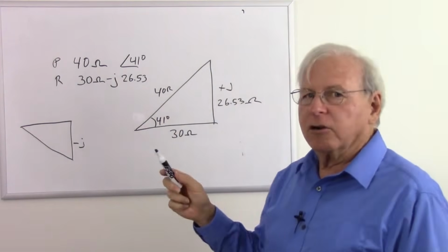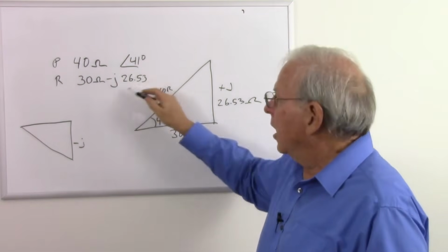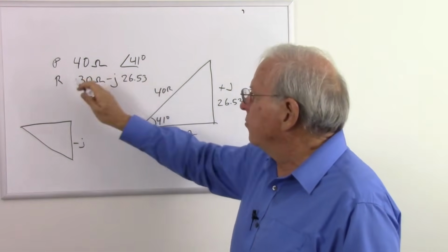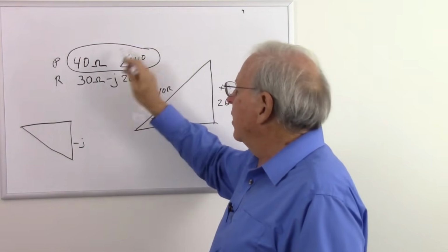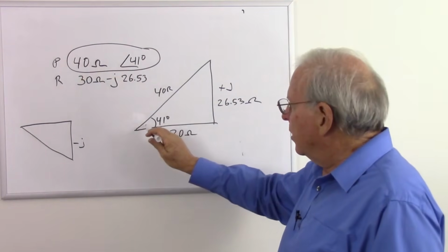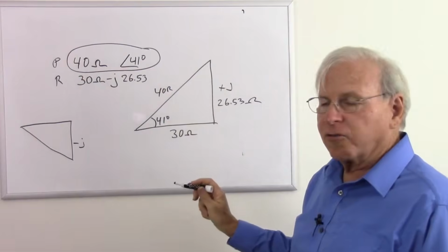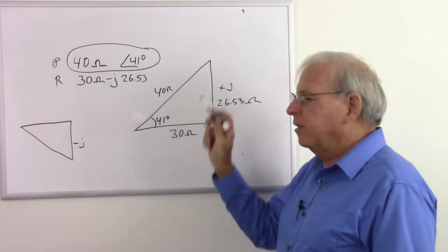And using this rectangular notation, if I have both inductors and capacitors, I can actually add those together. So sometimes this is useful, but typically we express an impedance as a number of ohms and a phase angle representing the length of the hypotenuse of our triangle and the angle between our resistance and our impedance.